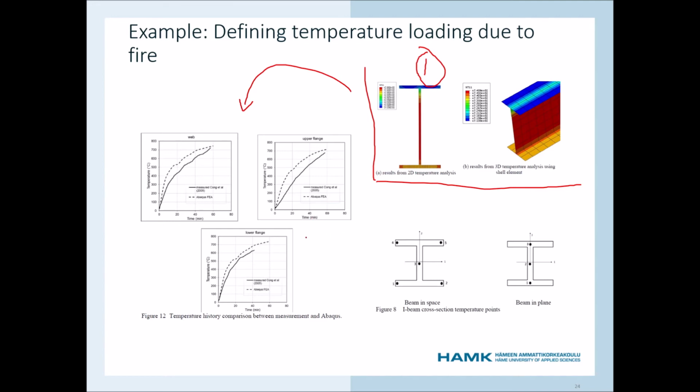simulation time. So we have this 0 to 2 seconds, where we have this mechanical loading step, and from 2 to 20 seconds, which is around 18 seconds, we have this heating effect. So this temperature curve, which we obtained from this thermal analysis, has to be scaled to that.